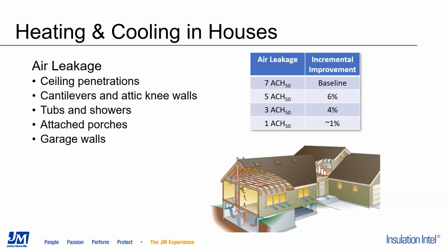And then finally, garage walls. Many of us have attached garages to our homes. There's a common wall there. Those walls are often very leaky. And not only is that bad from an energy perspective, but that means that the house itself will end up sucking on the garage and sucking in all the junk: car exhaust, fumes from the gas can for our lawnmower, cans of paint, fertilizer, you name it, whatever we have stored out in the garage. We're kind of drawing that all into the house. So it's really important that we air seal that off. And then